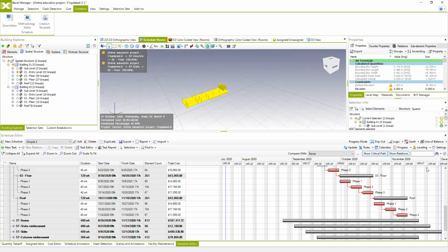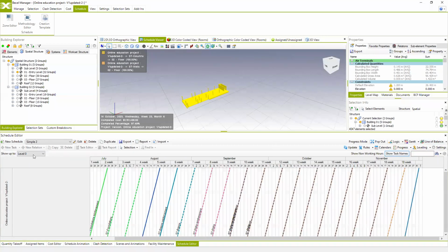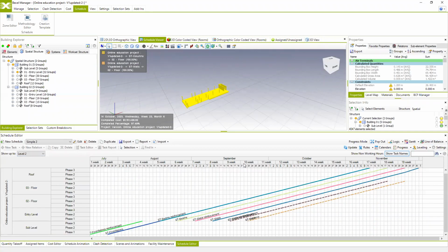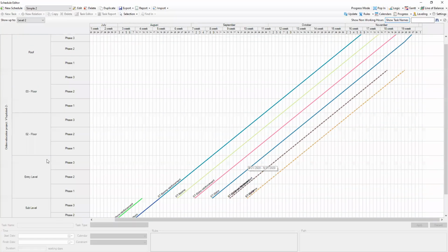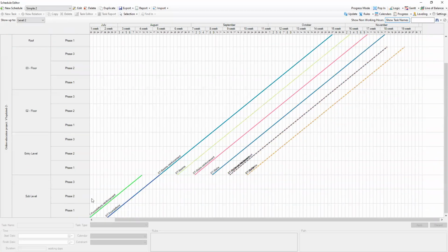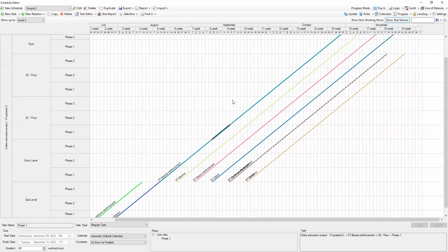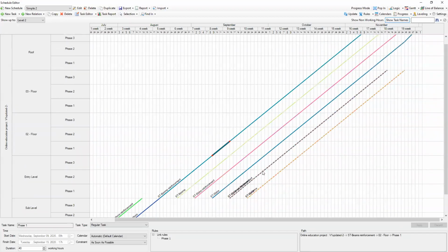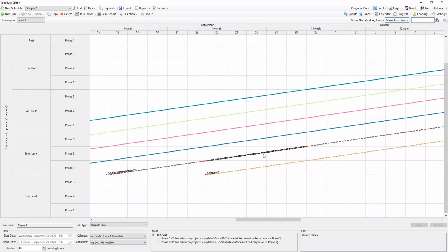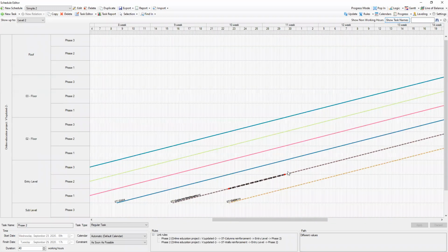And now when we check, for example, line of balance, because we already have a little bit more zones of segregation, you already see these activities. When you click on each of these activities, you can see the information about these activities and duration. And it already looks a little bit better. And of course, when these activities in the flow line are presented as a dashed line, it means that we have several activities overlapped, for example.